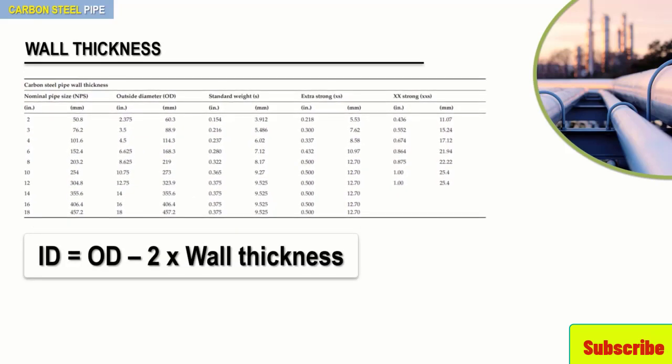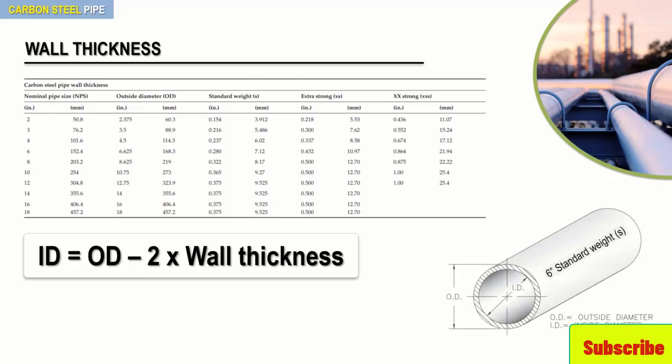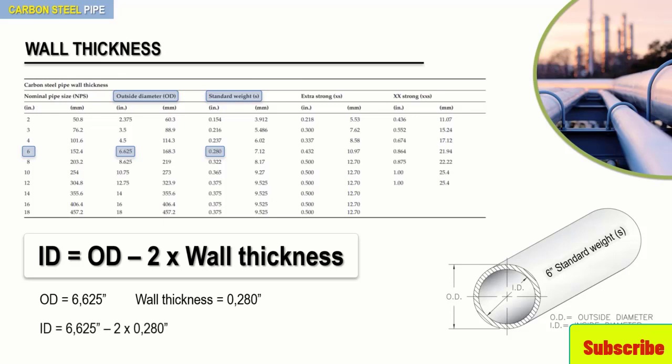Now, the formula that you can see here can be used to calculate the inside diameter of a pipe. Actually, the inside diameter is equal to the outside diameter minus 2 times the wall thickness. As an example, a 6-inch standard weight pipe will have a wall thickness of 0.280 and an outside diameter of 6.625. Now, substituting for the known values, we can then easily calculate the inside diameter. In our case, it is equal to the following.